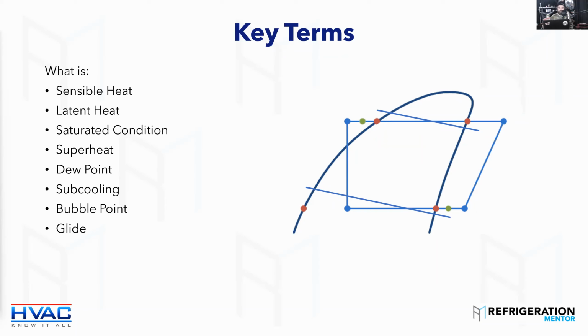evaporator temperature. And depending on what you're working on, your condensing temperature in AC is going to be 100 to 110 degrees Fahrenheit. So it doesn't matter what the pressure is. Maintain your saturated temperatures, and you'll be fine. And when you talk to other techs, use temperatures as well. I just find it's the best way to figure it out rather than relying on pressure.